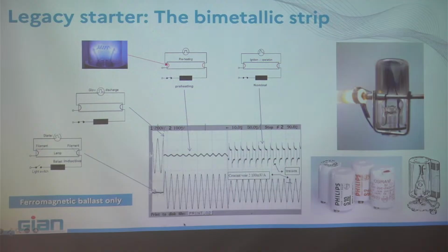That is for a sodium lamp, but in fact I could not find a video for a fluorescent lamp. But if you wanted to show that to your students, you take an old fluorescent lamp with the standard setup. I have that for my students in Toulouse, and I took one classic igniter. I get out the cap, and you can see the device inside, and you can observe the phenomenon. Look again. Plasma, the two electrodes touch, the plasma disappears, and the pulse goes to the lamp.